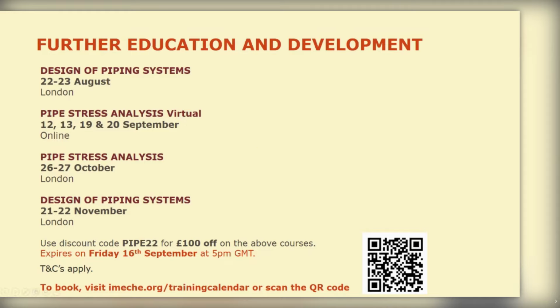Gary asks, why would you select EN versus ASME code? Thank you. Right, good. Very large question, really. I would say it depends what your specification is, where your plant is. If you're starting from scratch and there's nothing defined, it's your choice, so to speak. ASME in America, people use ASME. In the UK, oil and gas, people will almost always use ASME, with some rare exceptions now coming in. Petrochemical, a bit of the same.